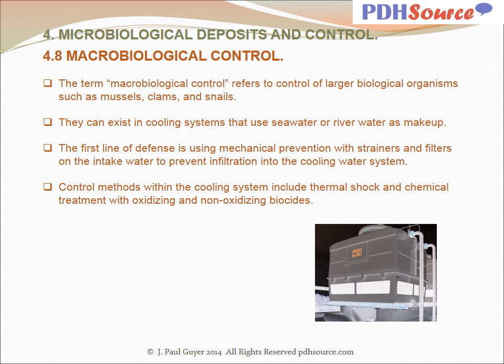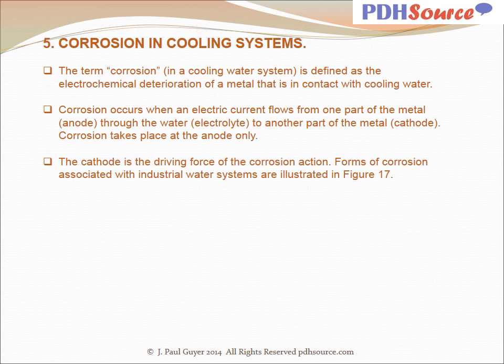The first line of defense is using mechanical prevention with strainers and filters on the intake water to prevent infiltration into the cooling water system. Control methods within the cooling system include thermal shock and chemical treatment with oxidizing and non-oxidizing biocides.